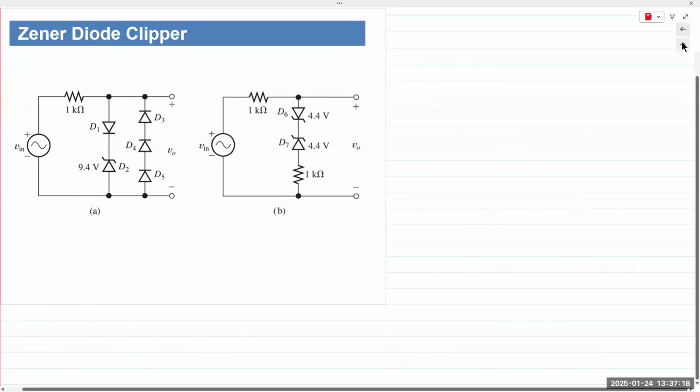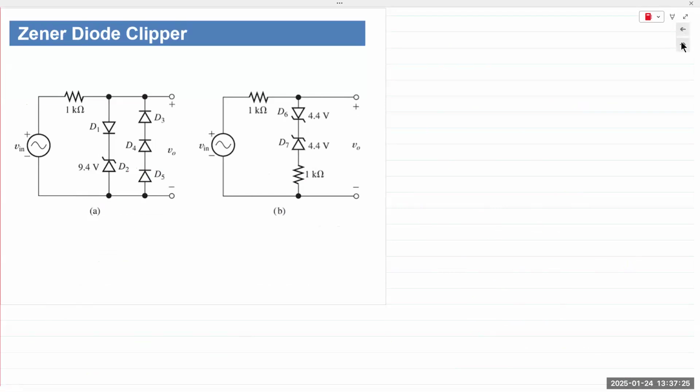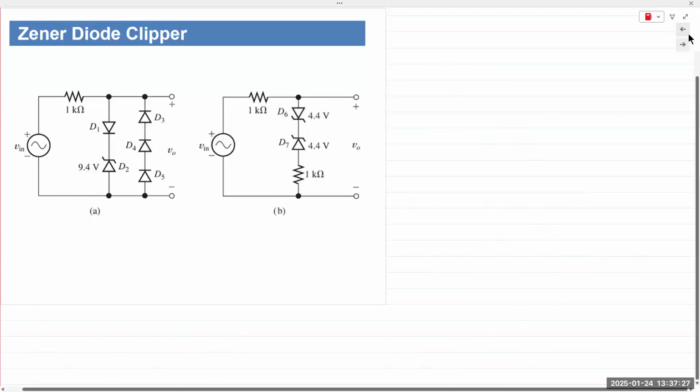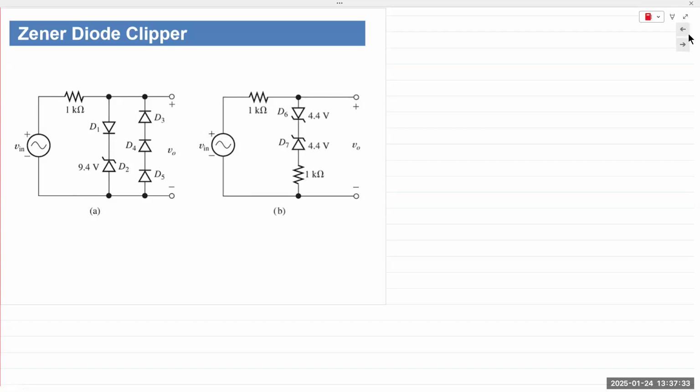What is different between these two circuits? There's only one Vin. There are no DC power supplies in the second one. So obvious downside in the first circuit, just plain silicon diodes, is that we require a battery or a DC voltage source, right? Without a DC voltage source, we cannot create a Clipper circuit.